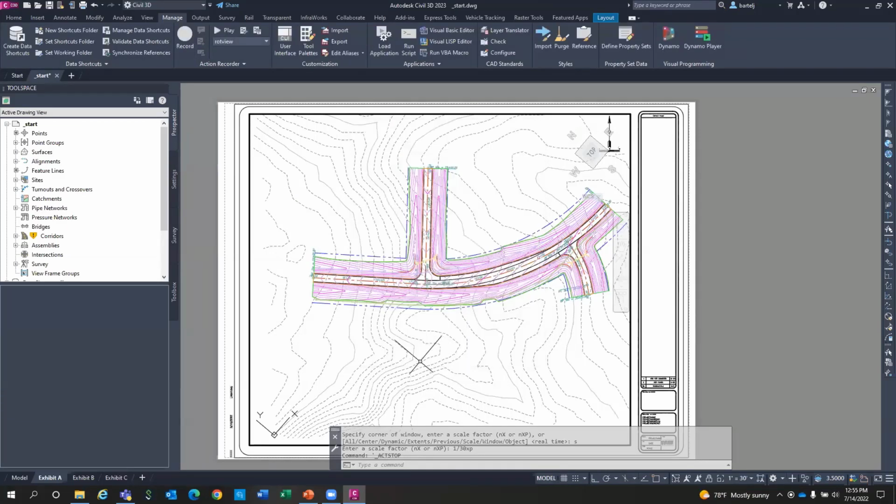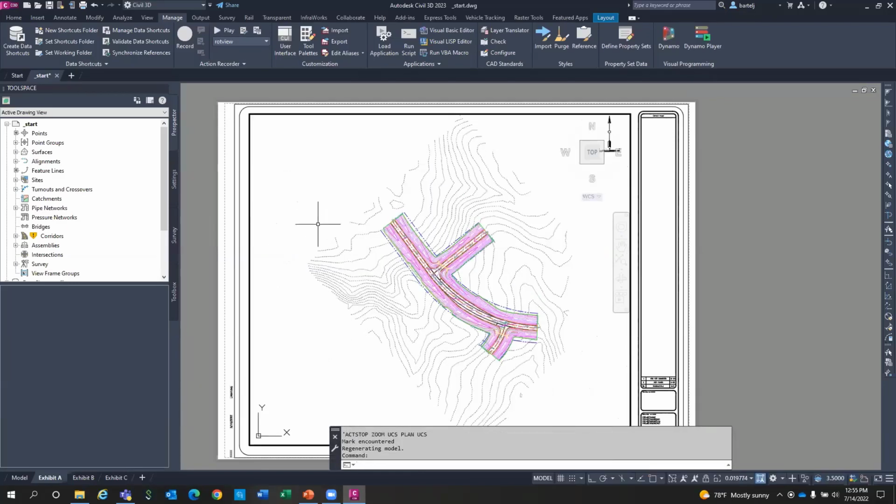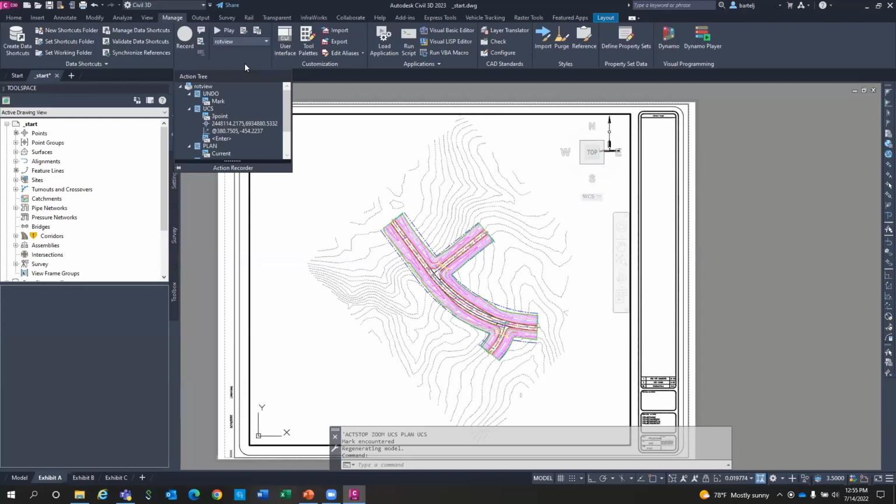We'll say OK. I'm going to say undo back so we can back up to this. Let's look at the command. Undo mark UCS 3 point. Well, I don't want to use the hard-coded ones that we had. So I'm going to say pause for user input for the first point. I'm going to say pause for user input for the second point.